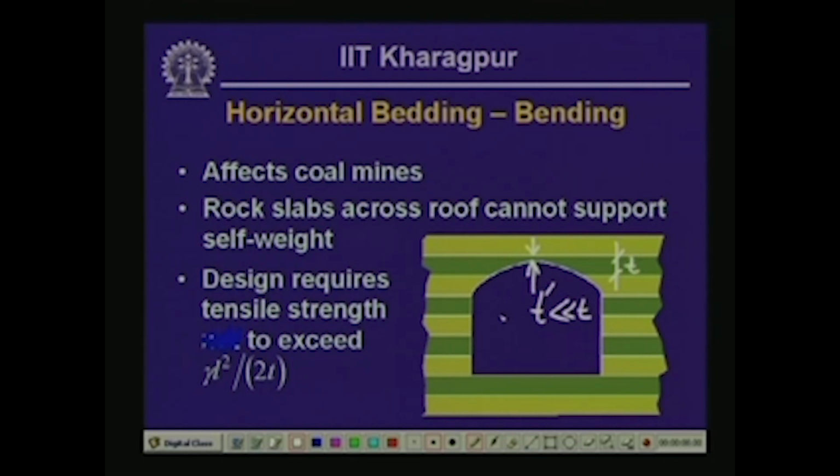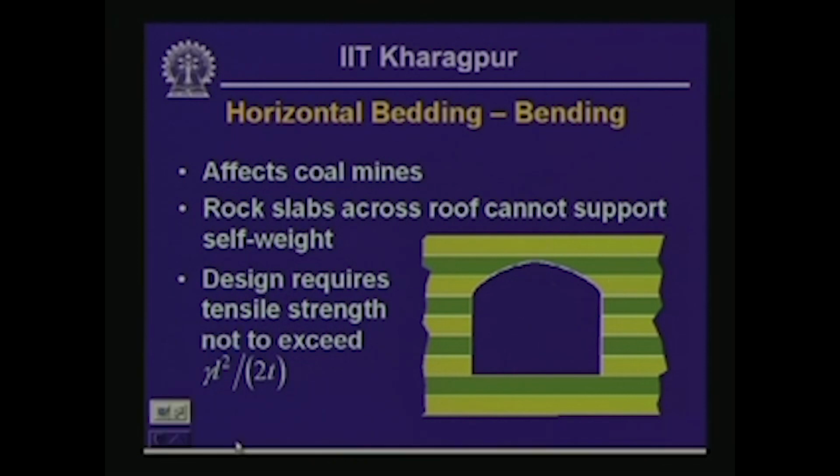As a result, the stability of the slab near the crown is going to be compromised quite severely if this type of tunnel cross section is chosen. So, the bottom line is in this case a square cross section of the tunnel is preferable.